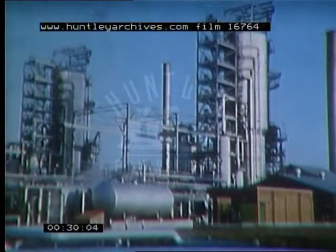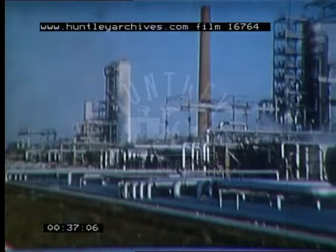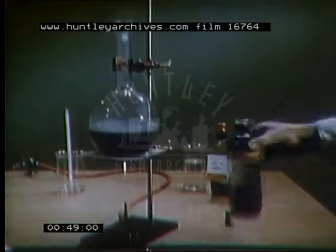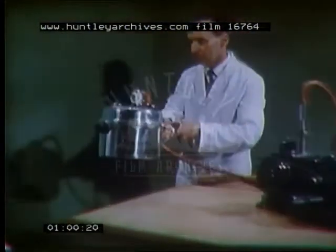The vacuum distillation unit continues the processing of the residue from the crude oil distillation unit. This residue is known as atmospheric residue, since it comes from the second tower of the crude oil distillation unit, which operates at atmospheric pressure. We are heating a sample of this residue, but it is chemically decomposing, or cracking, instead of boiling, and cannot be distilled. This experiment, in which a pressure cooker is connected to a vacuum pump, shows the way in which we overcome the difficulty.